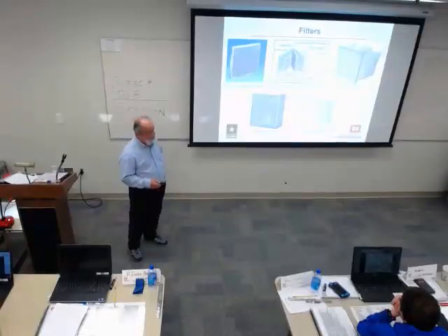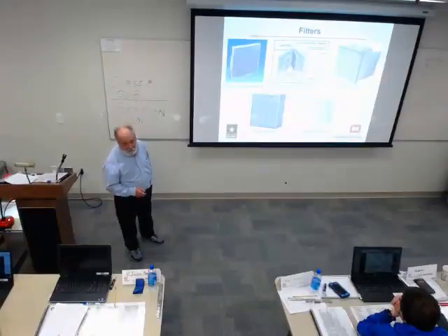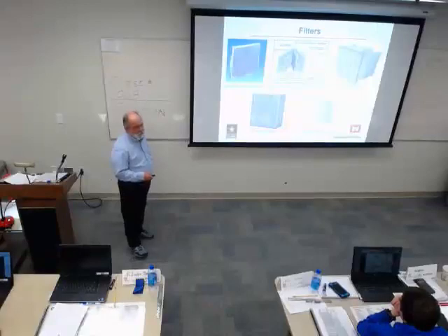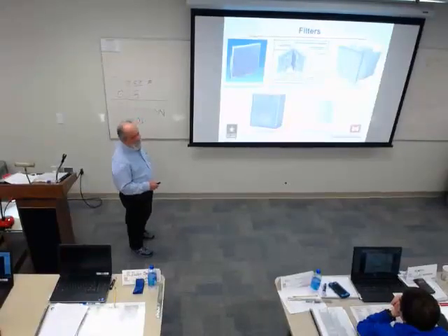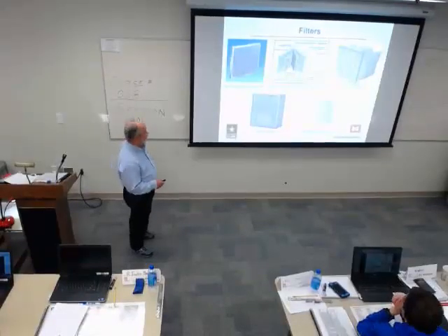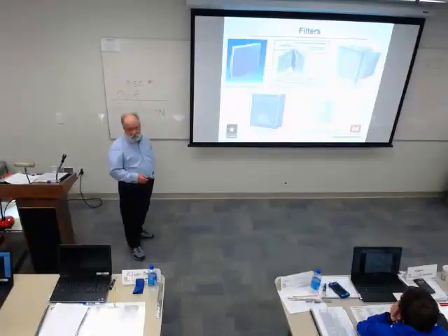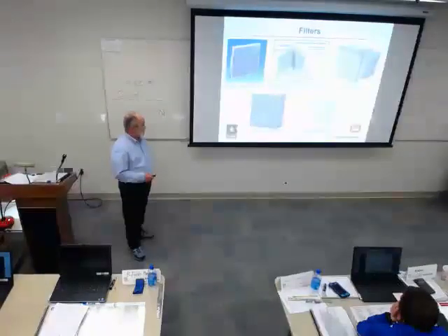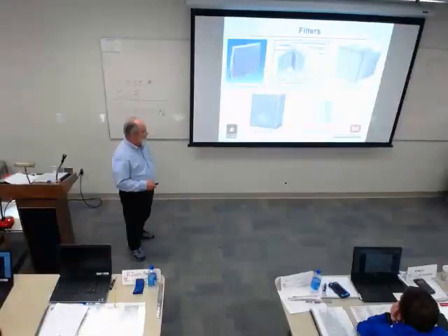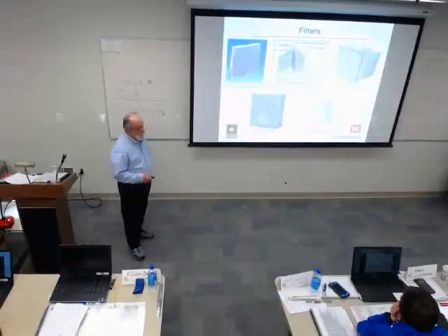Bag filters give us extended surfaces, which amounts to lower velocities through the filter, which gives us, for the same amount of filtering, lower pressure drop. Then we have the HEPA filter, and that's for the high efficiency requirements we sometimes have. And then the pleated media.